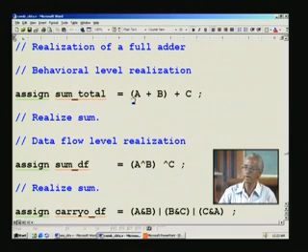So, you have to tell the synthesis tool to do this in parallel with this. That means, here it is redundant. If you had one more, C plus D, you can put another parenthesis, then C plus D and A plus B will be done simultaneously. And we have also seen that earlier, in RTL coding, precisely that example. The same end result can be achieved in two other ways.